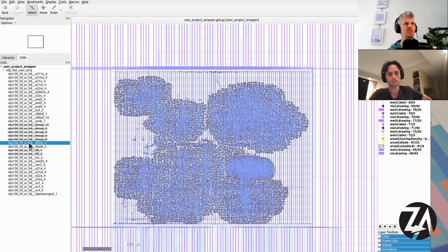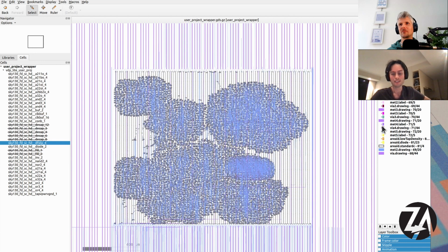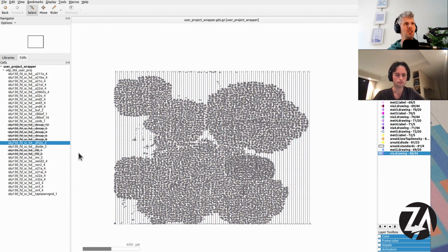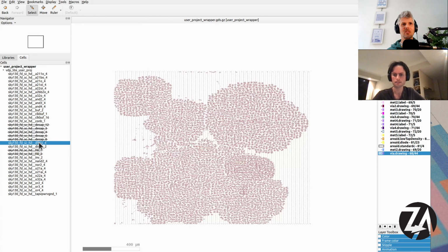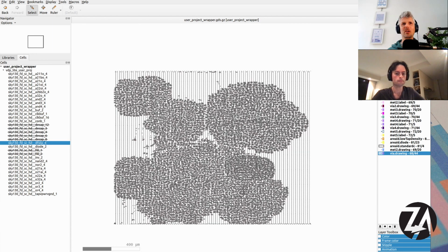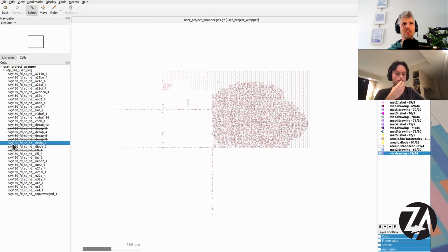That's interesting. I don't think I've ever tried filtering by flip-flops. I'm guessing one of those large clouds, or two of them, are where the 512 flip-flops are, and there's a few more for sprite memory and attributes and all the rest of it. If I spent a bit more time, I could find out where they were. They look fairly evenly